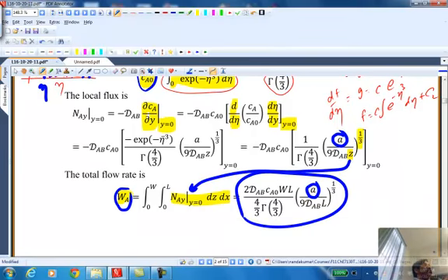So that net flux rate should depend on, that's a good way to look at it intuitively afterwards. What should it depend on? It should obviously depend on the diffusivity, it should depend on the solubility, it should depend on the total area. W times L is the interfacial area between the solid and the liquid, the depth W being perpendicular to the board, and L is the length along the liquid film. And it should also depend on the velocity profile, particularly the velocity gradient, which is A in this case.